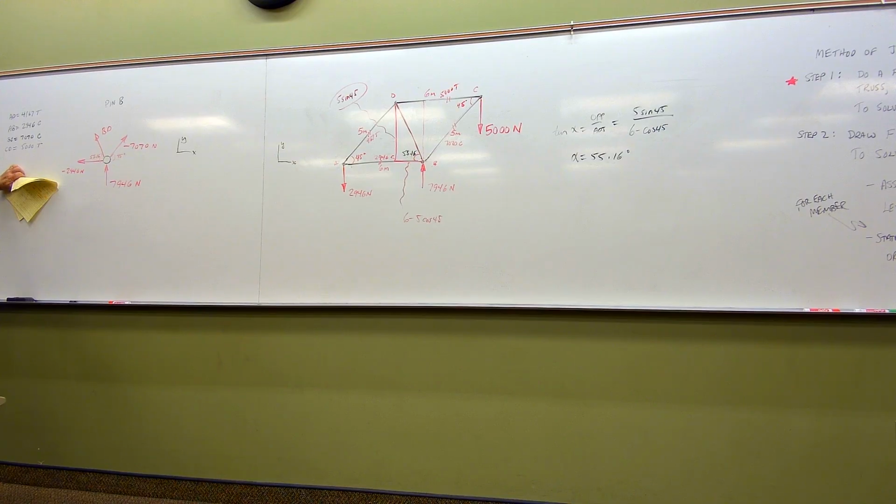In fact, all I need to do is sum forces in the x direction, and I should be able to solve for BD. I could even just do the same with summing forces in the y direction. I can solve for BD. So either way is a winner. Let's just sum forces in the x direction.